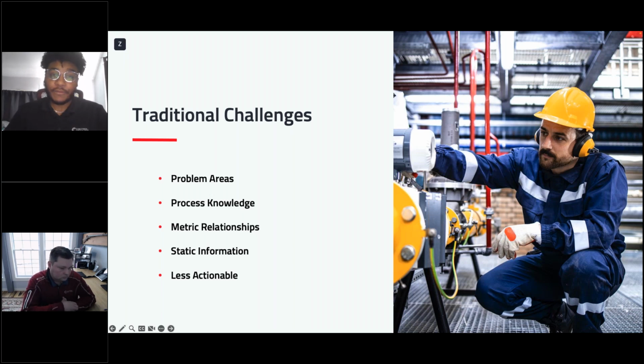It can't tell you whether the excessive movement you're seeing in a final control element is par for the course in anticipated behavior, or whether it's something that needs to be addressed by you. Nor can it tell you whether a valve that's been saturated at 100% output for a few hours or a few days is actually totally fine, because it only triggers when the process gets above a certain threshold, right?